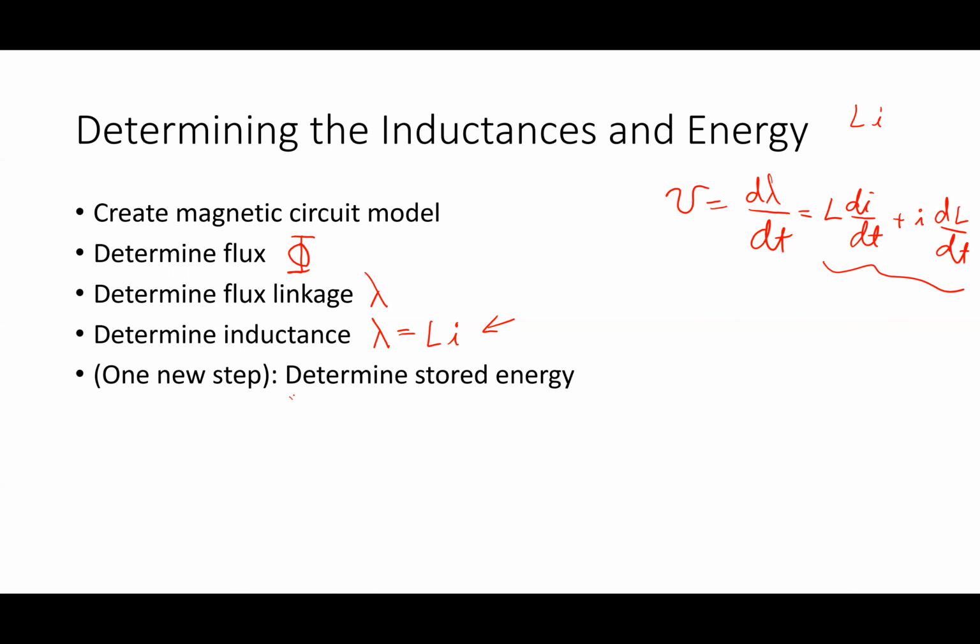And then to get to a force, what I've got to do is calculate the energy. Now, you guys learned a formula, which we're going to kind of derive a little bit today, for the stored energy, which I'm going to write like this: the energy stored in the magnetic field. What's the variable W for? Work. All right, energy and work. We probably could use E, but E is often used for voltage in the context of magnetic stuff. So I use W to be energy, or work.